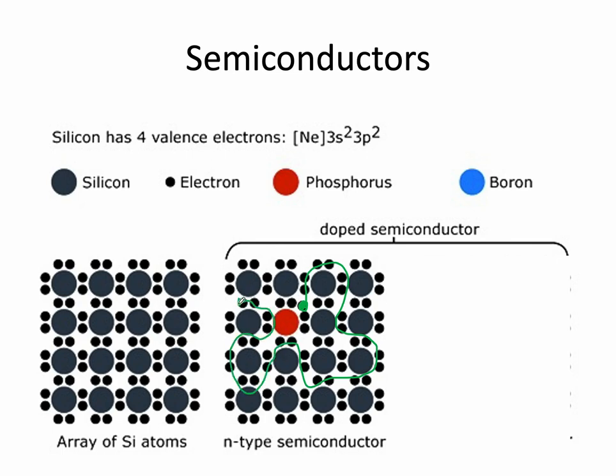What do you call a material where you've got free mobile charges? It's a conductor. And so when you have this extra electron in there, this whole crystal becomes a conductor because I've got mobile ones. And usually you end up doping it with quite a few phosphorus atoms, not just one. Because it's got extra negative charges in it, we call this an N-type semiconductor. Negative extra electrons, N-type silicon or semiconductors.